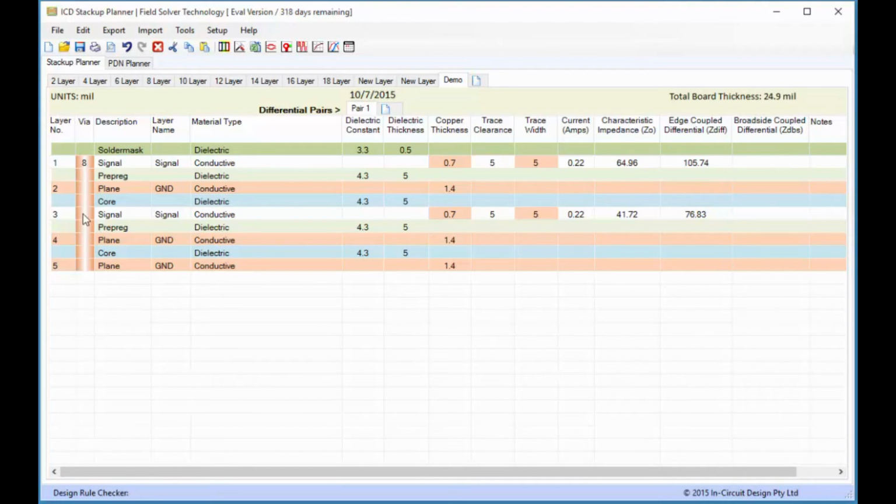And as a matter of fact, and I'll go into a little bit more detail about this when we talk about the vias, what we want to do here is ultimately keep as many of our traces as possible on the top, between the top layer and layer 3. And yes, we may have to send traces down to the bottom, but we want to minimize the amount of traffic that goes between the top and the bottom as much as possible.